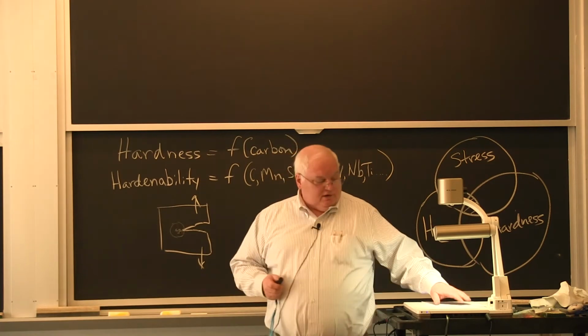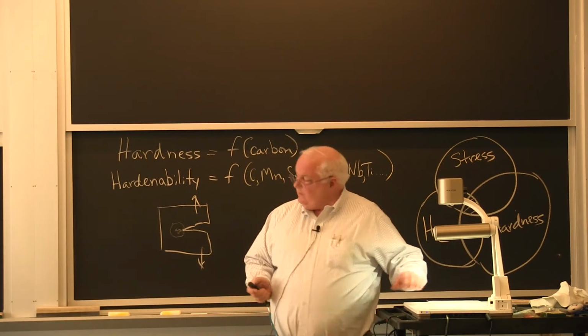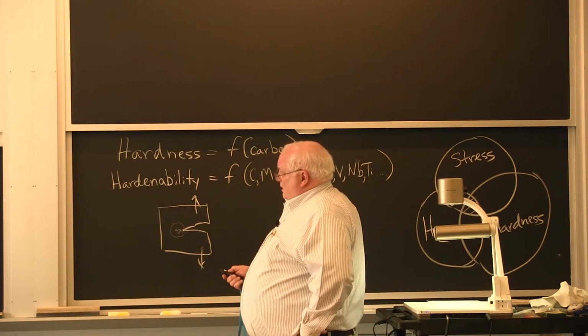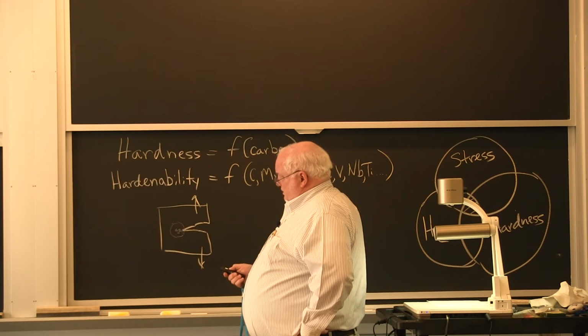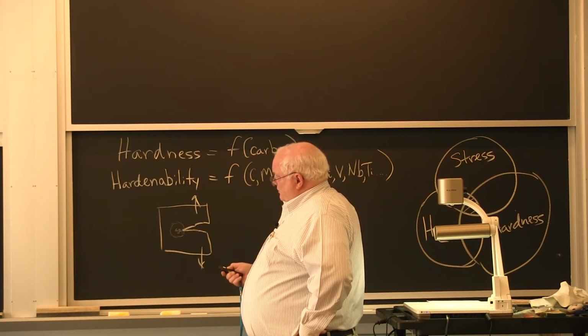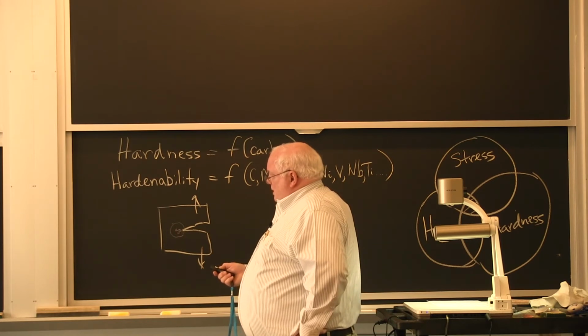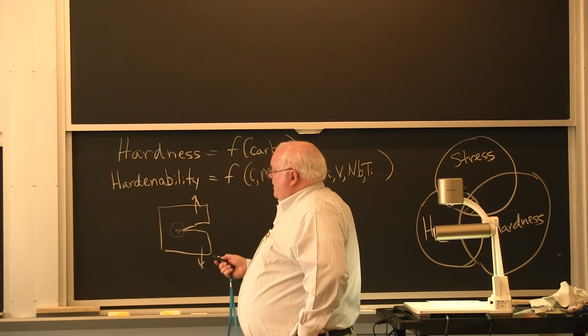So here is the iron-hydrogen phase diagram, and we'll come up with some numbers here of how much hydrogen will be in the steel. I've done the 1 atmosphere curve. This is a plot from Carl Zaffe, who was a hydrogen cracking expert 50, 60, 70 years ago. 1/10 of an atmosphere, 1 atmosphere of hydrogen, 10 atmospheres, 100 atmospheres of hydrogen. As a function of temperature, here's the melting point of iron.